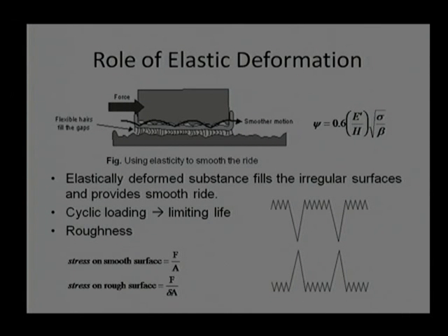Now, this whole slide was related to surface roughness, hardness and Young's modulus. It has been experienced that surface roughness plays a major role compared to the other properties, Young's modulus and hardness. The reason is that surface roughness will continuously change. Initially, maybe surface roughness has a value of 1. After some operating hours, the surface roughness value will change.